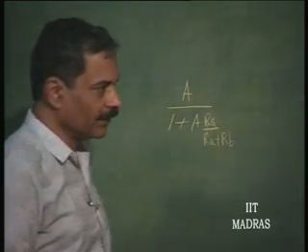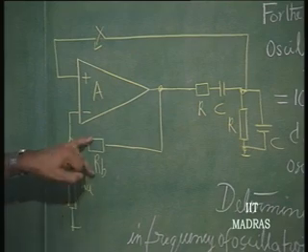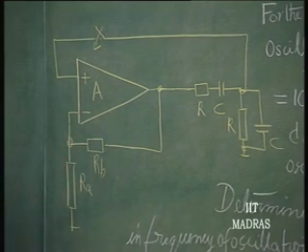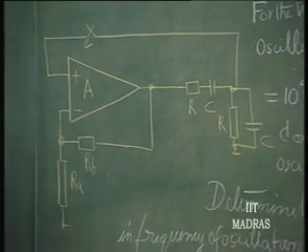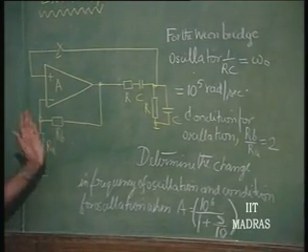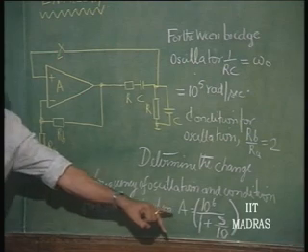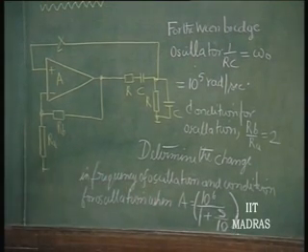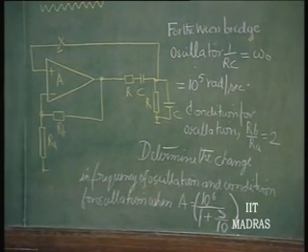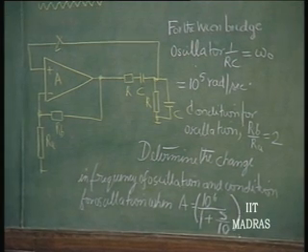That in this particular case is going to be nominally equal to 1 by 3, because of that condition. It might not change, it will become less than 1 by 3. So, the gain is greater than 3 for making this get satisfied, that finite gain comes into picture, and therefore, you need a slightly larger gain than 3 in this case, that we will see later.